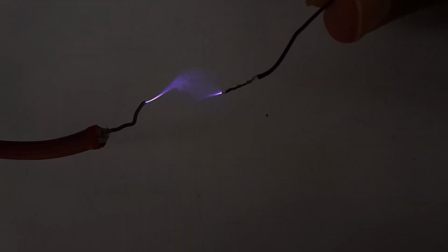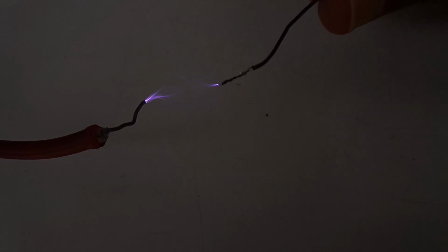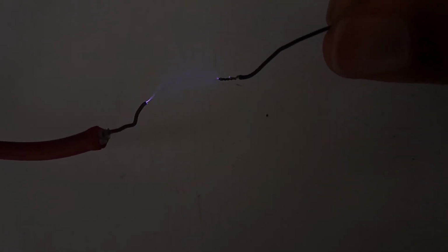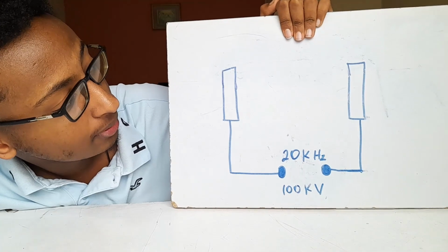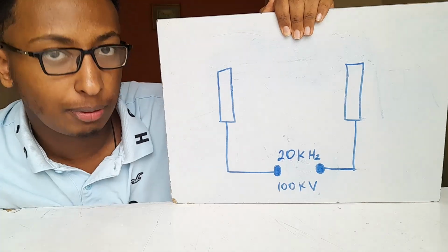Just like I said, the color appears to be violet or purple, and there's some amount of heat on the anode of the flyback transformer. It's warming up, but not on the other side, which indicates that this is a DC flyback transformer. The UV is invisible, but we can see it by the reflection off a white object, such as a paper.